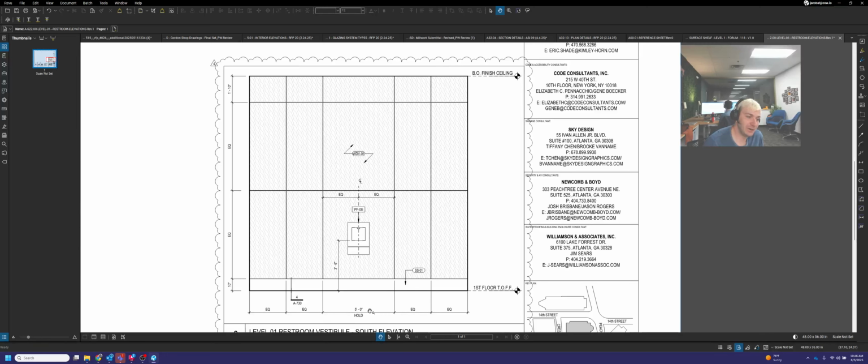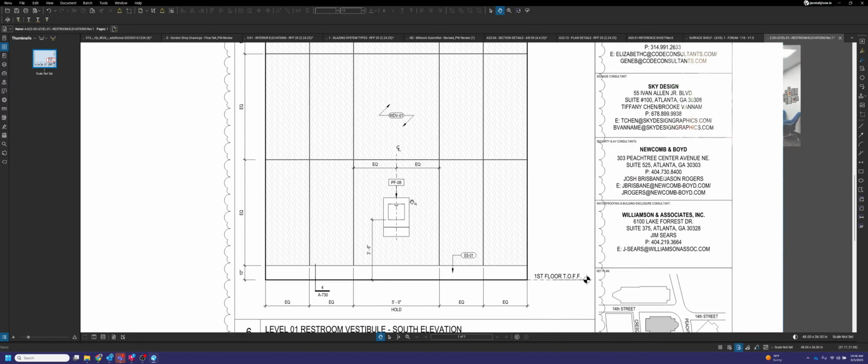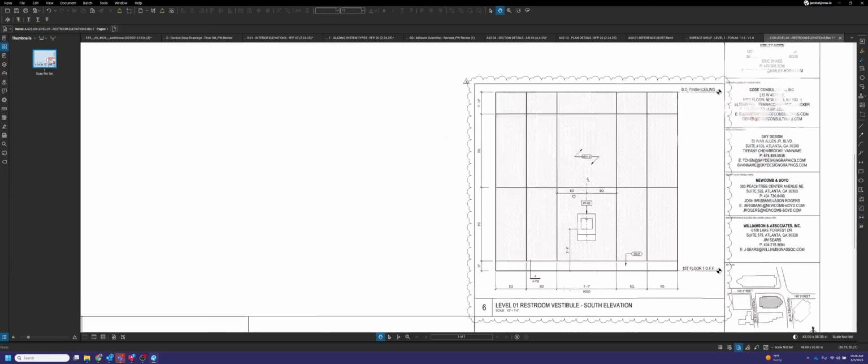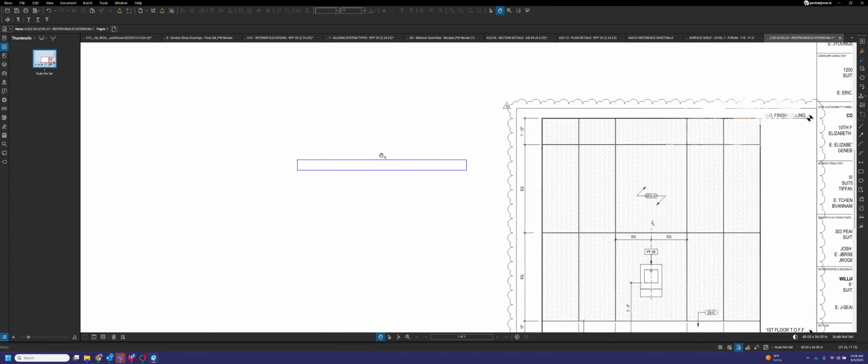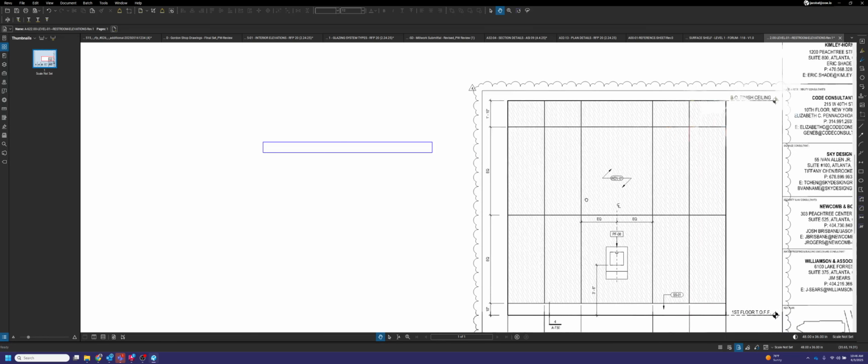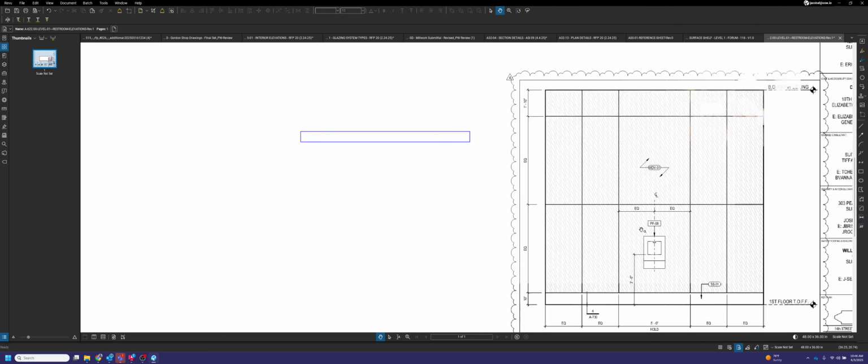Now, if they don't go for it, we can actually produce panels that are wider than 48 inches. It's just more of a hassle. We may have to do what's called a shop joint. In a shop joint, you have two panels that are coming together and they're glued and attached together in the shop itself. So it looks and feels like a full panel, but really it's two panels, and the joint will be covered up by the veneer, so you never actually see it.